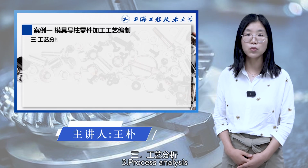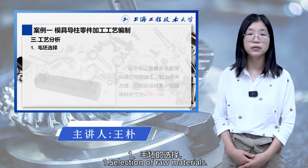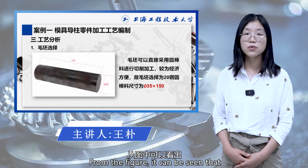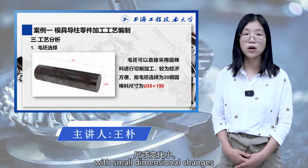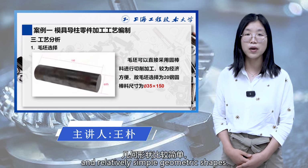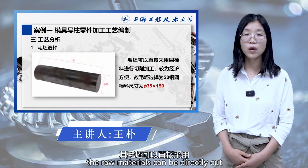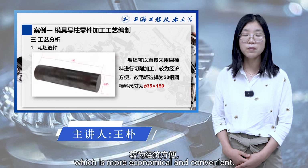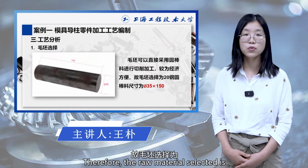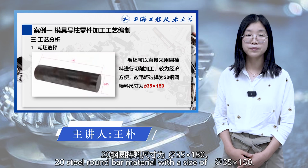Third, process analysis. Next, we will conduct a specific process analysis of the parts. First, selection of raw materials. From the figure, it can be seen that the maximum diameter of the guide pillar is 30, with small dimensional changes and relatively simple geometric shapes. Therefore, in single piece and small batch production, the raw materials can be directly cut with round bar material, which is more economical and convenient. Therefore, the raw material selected is 20 steel round bar material with a size of 35 × 150.